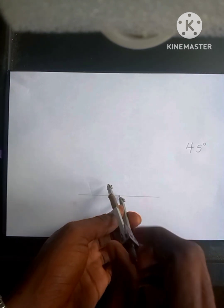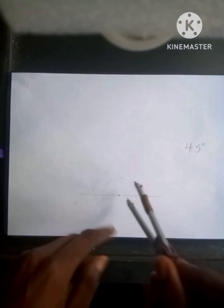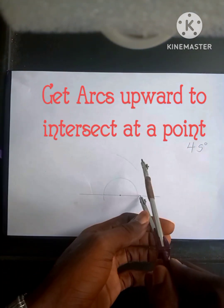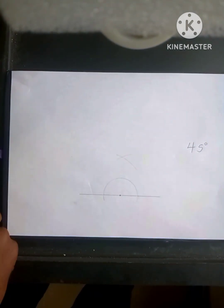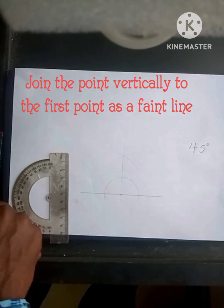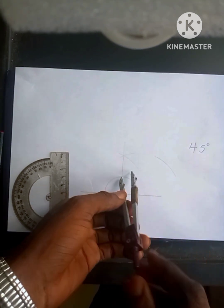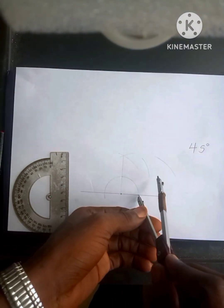Take any small radius, put it at the point you marked out, and draw a semicircle. In this one, what you have to do is increase the radius, maybe twice the radius. Put it at the two points of intersection to get an arc upward, no more on the semicircle but upward. Twice the radius: if you used 2 before, you now use 4. Now join the points vertically to the point you marked out. That's 90. Now for the two points, the first point where the circle intersects with the line and the semicircle, make sure you are using the same radius. If the radius changes, you take another radius.